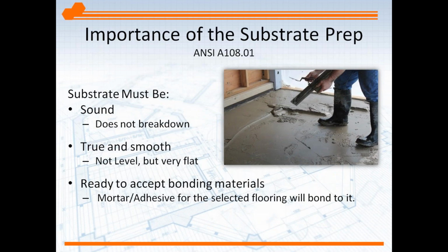Let's start at the start, the substrate, right? The substrate is always important for any finished flooring, but certainly as the tiles become larger, it has become even more critical. So ANSI 108.01, the standard for preparation of a substrate, says that the substrate must be sound. Certainly, we don't want that breaking down or chipping or spalling. It must be true and smooth, which would not necessarily mean level, because we may not want it level. We may need a pitch for some reason, pitching to a drain, but very flat. Ready to accept bonding materials.